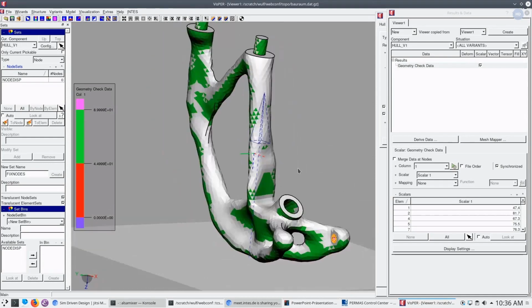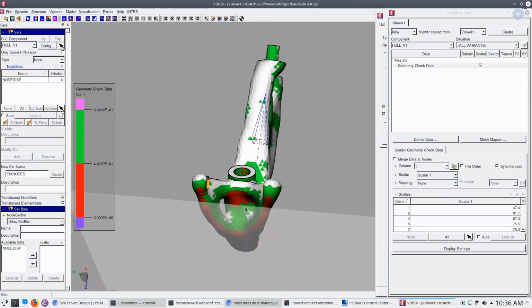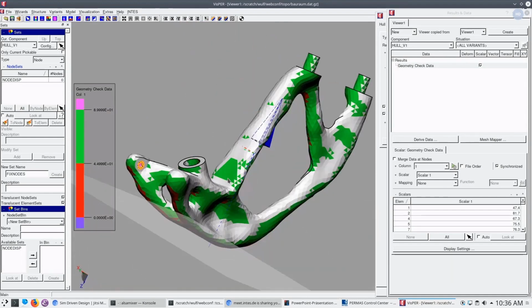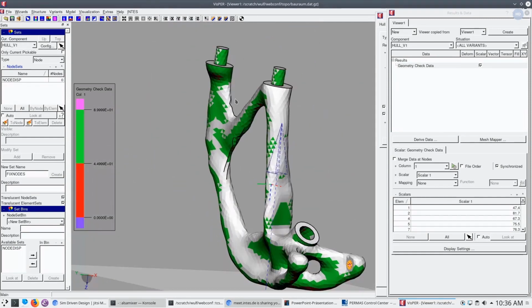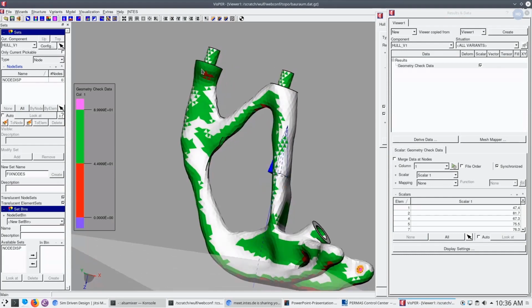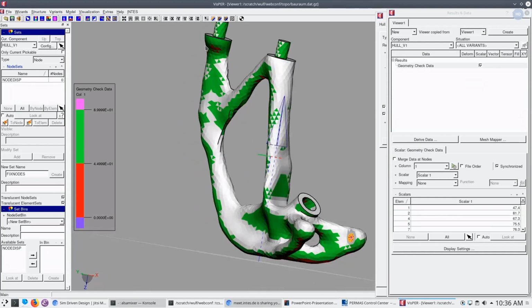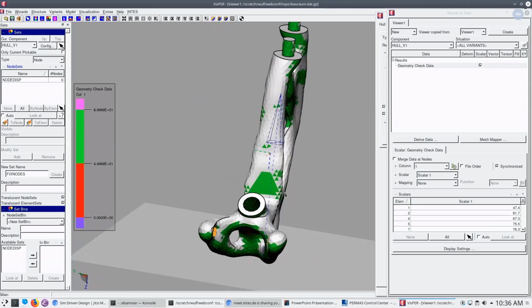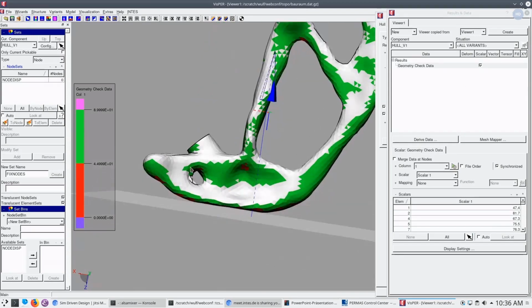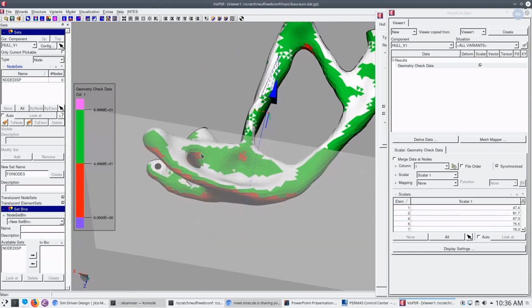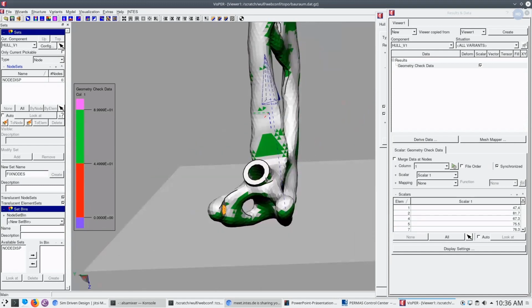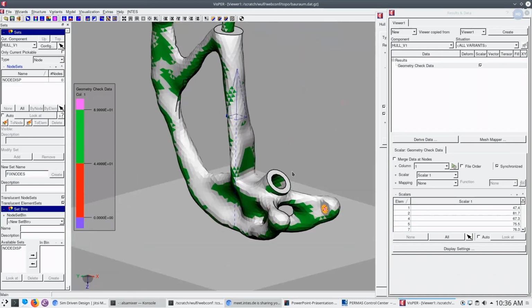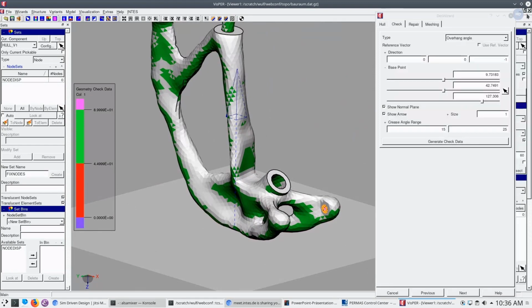And of course we also have a problem here in this area, and maybe this can be simply done by a shape optimization to change this angle here. But here, if you want to avoid the need of support structures in this area, you see here indicated in red, you need a different topology, because the hole here should be closed. So with this in mind, we go back to the previous model.